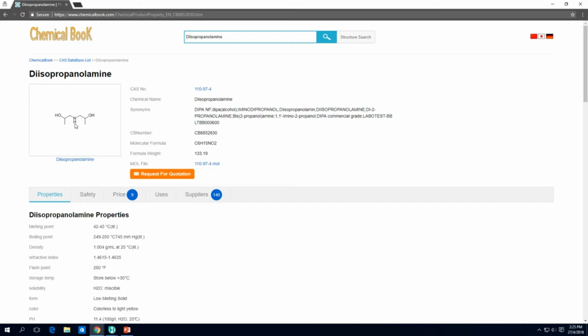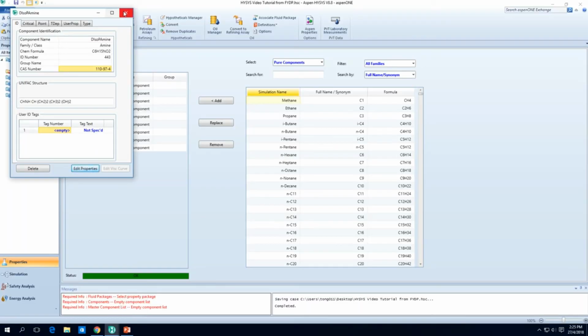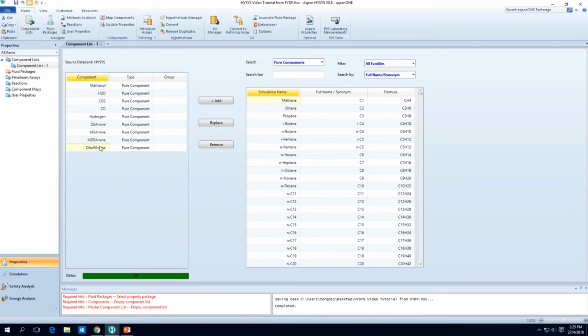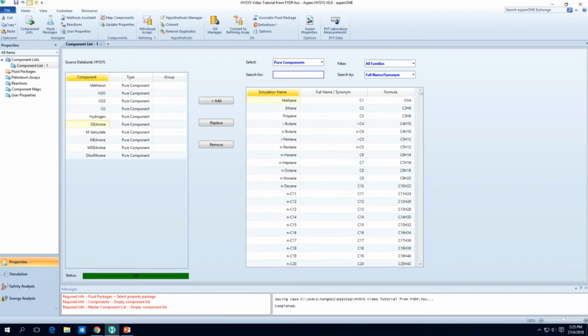So we'll probably be looking at DIPA. On top of that, we'll probably have to add some of the actual acid gases that we are capturing. I'm going to add a bunch of other gases commonly found in flue gas. For example, besides CO2 and CO, you'll have the usual oxygen and nitrogen.